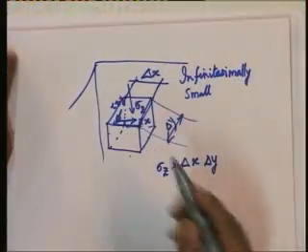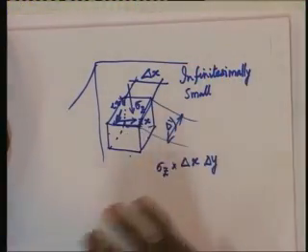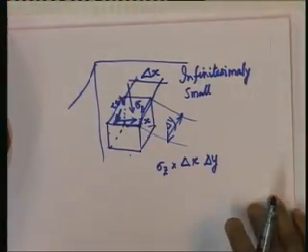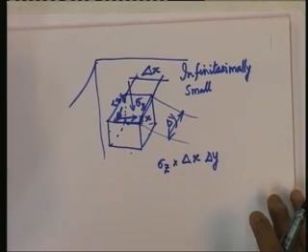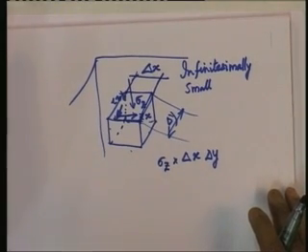Now, it is very important that this element be kept in equilibrium by these forces. So, what could be better than simply writing equations of equilibrium for all those forces which are acting on the various surfaces of this element? What could be the equations of equilibrium for a 3-dimensional problem like this? There could be 6 equations of equilibrium, 3 for force equilibrium and 3 for moment equilibrium.